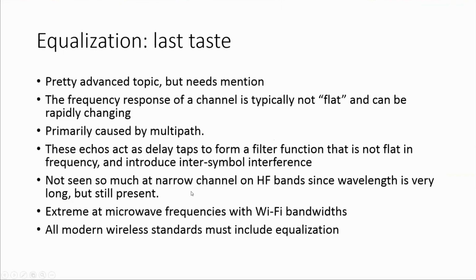At HF, we don't really ever experience it because the wavelengths are very long, but you could, if you tried to implement a digital communication scheme, have an issue with this. And some of the ARQ methods that are used, especially in marine transmission, do have to deal with that. At microwave frequencies, because the wavelengths are short and the bandwidths are wide, it is absolutely necessary to fix it.